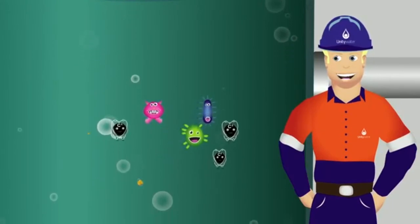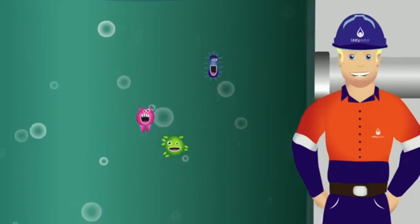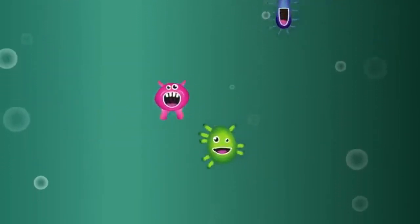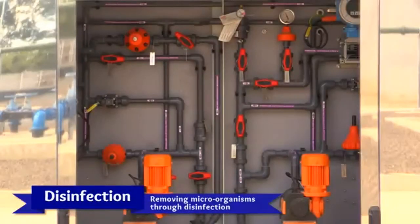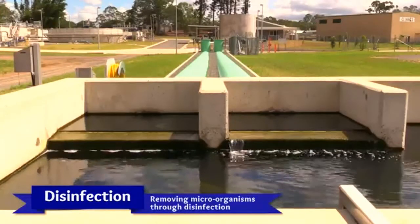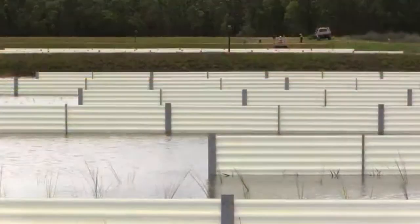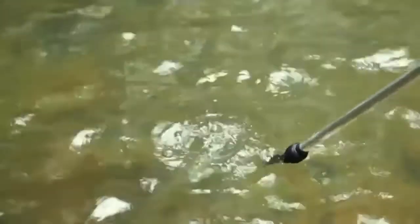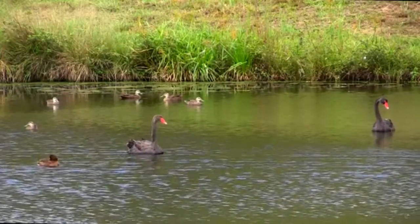That's right. These guys eat all the carbon and reduce the amount of phosphorus and nitrogen in the sewage that can impact the health of our waterways. So we feed them in huge bioreactors filled with lots of oxygen. They can eat and breathe and have lots of hungry babies that eat more and more and more. By now, our treated sewage is looking pretty good, but we need to make sure it's ultra clean. So we filter it, then we disinfect it with ultraviolet rays or chlorine to reduce any hidden germs or nasties that might have snuck through. All the way through our treatment processes, the treated sewage is tested to make sure it meets strict rules. At the end of the process, the treated sewage is called effluent and it's been tested for quality more times than bottled water.